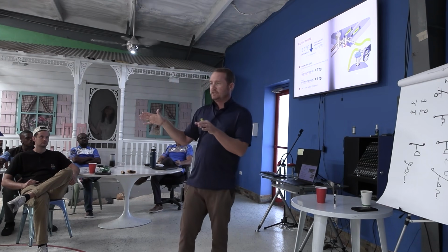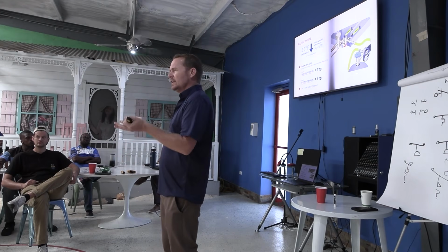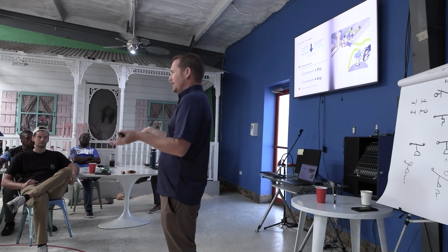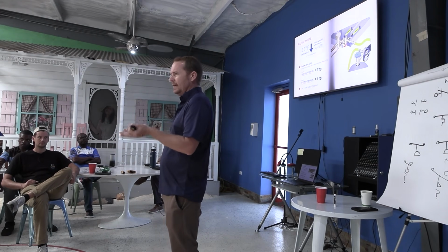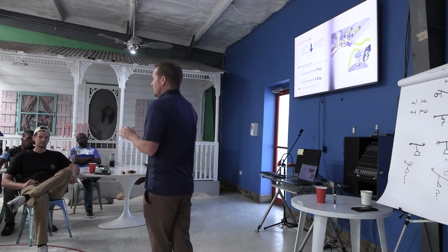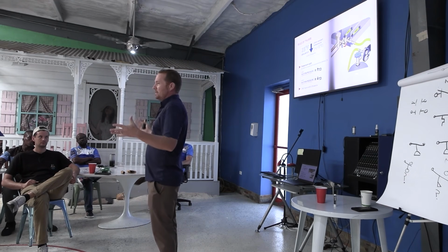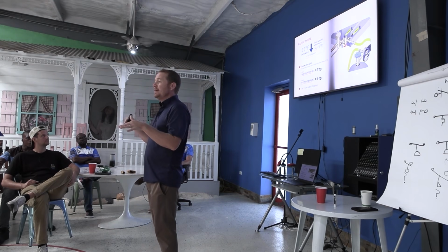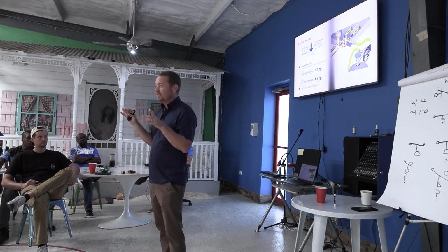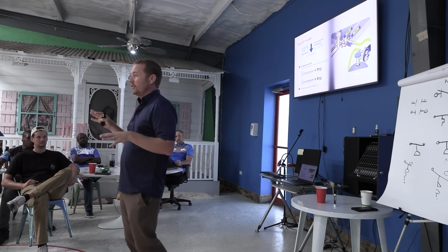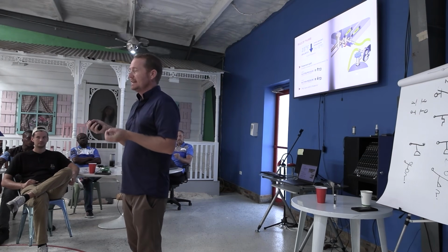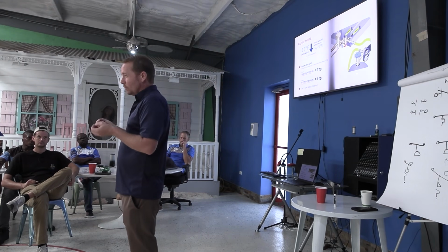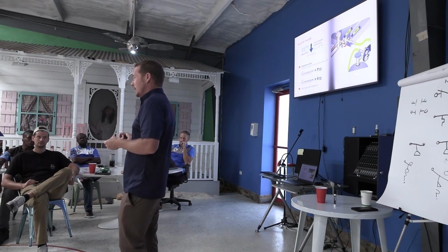I'm going to ask this to you guys, though, those more senior techs. Do you see it a little higher than that? Are you seeing evap temperatures that are a little bit higher than that? That's what we see, too, because evaporators have gotten a lot bigger. So in an ideal world, you may see that that number is more like 32. In some cases, even 30, but that's not great, right? Because that indicates that we aren't running cold enough coils to do a really good job of dehumidifying.